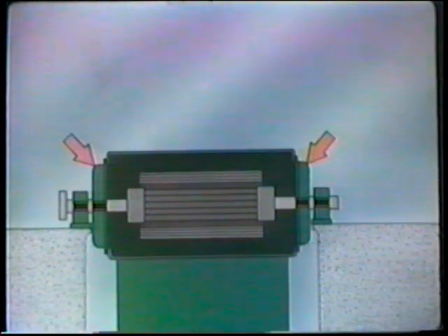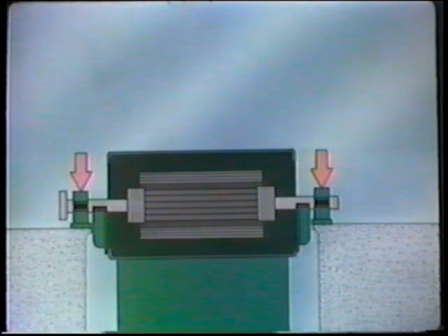The end bells of a large generator usually come in two separate pieces, an upper half and a lower half. Now the next step is to unbolt and remove the upper half of both end bells. The lower halves won't be removed until later on. Next, the bearings are removed. The bearings also come in two halves. The top halves can be removed simply by unbolting them and lifting them off. But the rotor rests on the lower halves, so the rotor will have to be supported before the lower halves of the bearings can be removed.